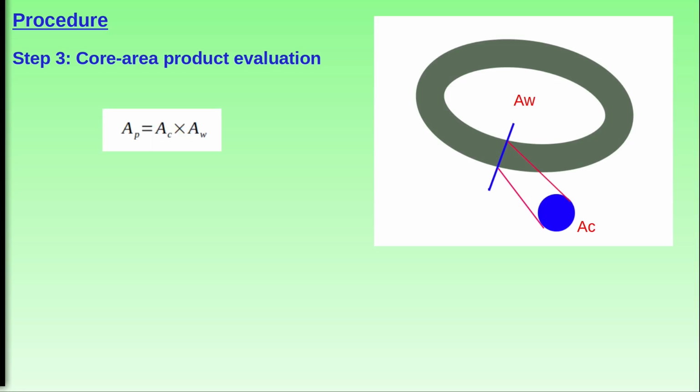This entity correlates directly with the power VA that we calculated in the previous step. The correlation is through Faraday's law, adjusted to consider the mechanical measurements, the power of the transformer, and the maximum amount of flux that the core can handle without having its magnetic capabilities altered forever. You can compare the max flux that a core can handle with the max amount of current that can flow through a wire. The max current depends on the sectional area of the wire and the material, whether it's copper or aluminum or a different compound.